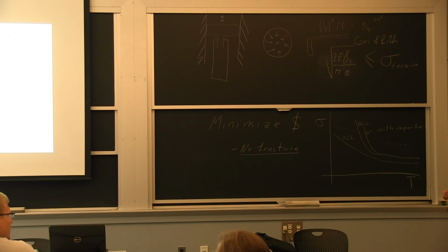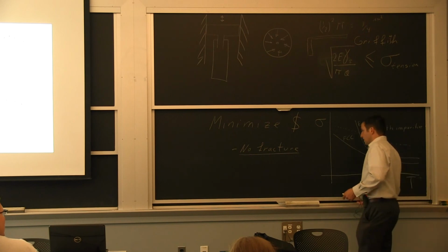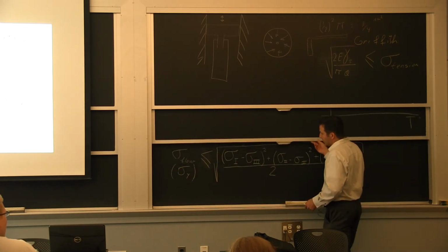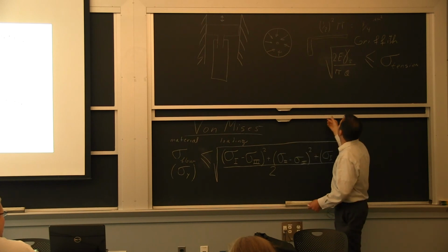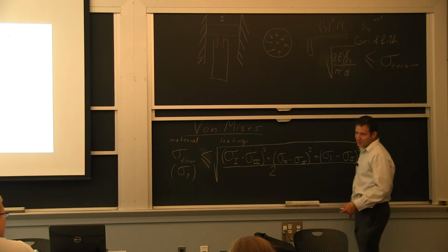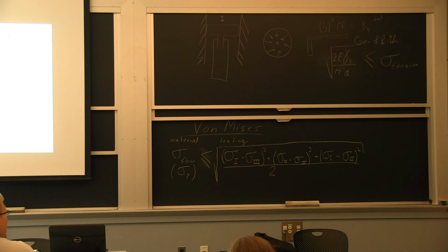A lot of aluminum castings are notch sensitive because you can increase this by having a very fine casting structure or by making martensite, but you're not going to increase this one. It's the same way. So trying to work the Griffith equation with metals is pretty difficult.